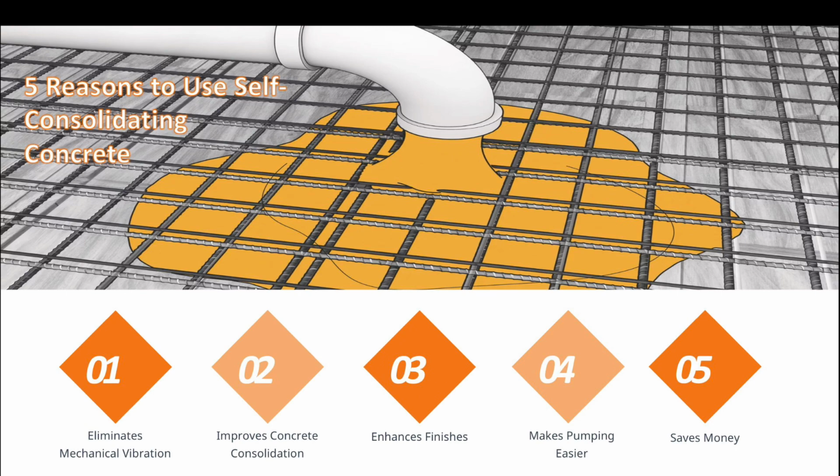SCC's impressive flowability promotes successful consolidation around dense, concentrated reinforcement. For example, SCC makes it possible to successfully fill areas unreachable with internal poker vibrators. It allows for denser reinforcement, adding strength in the process. Number 3, it enhances finishes. Architects enjoy increased freedom of design for a number of reasons, including increased options in formwork orientation. SCC can also be placed in intricate molds that would not work with conventional concrete.